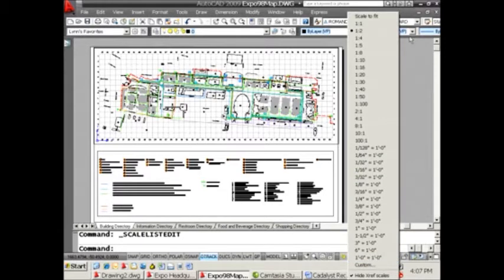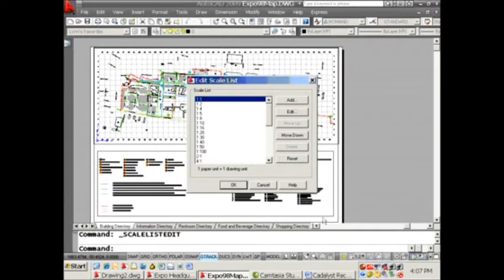So taking a look at this list, this is a pretty big list. I'm going to guess that you do not have all of these different scale factors in your drawing. So I strongly encourage you to select the Customize option and decide which one of the scale lists you actually use and get rid of the ones that you're not. For example, maybe you only work in metric and you don't work in imperial at all. Just go through here and delete any of these that you know that you're not going to be using. It's no problem if you decide that you want to put them all back later on. There's this great reset button that puts you back to where you started.